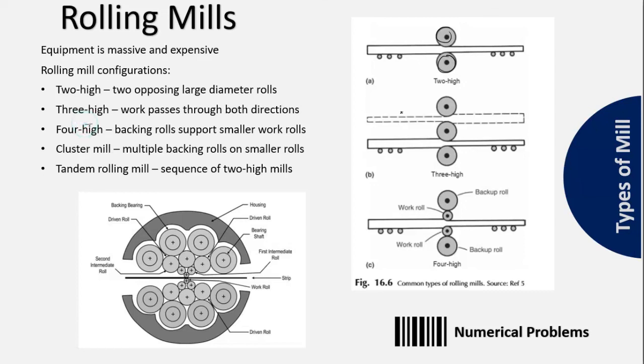We have the three-high rolling mills. Two rolls are exerting the pressure, and we have a platform here. Once the workpiece gets here, this platform transfers the workpiece to the upper level, and then there's another pass on the third roll. We can have the four-high rolling mills, in which there are two back-up rolls exerting pressure onto the smaller rolls, right? So that can perform the rolling operation. The purpose is to reduce the roll force, because the diameter is reduced, so a lower roll force is required.